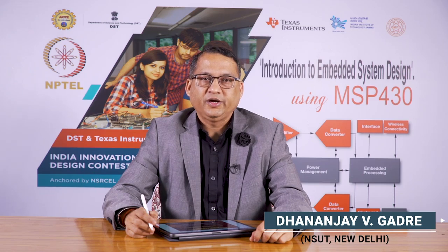In this session we are going to talk about one of the peripheral functions of a microcontroller, namely communicating with the outside world. If a microcontroller wants to communicate with the outside world, there are many ways of communication, but the common methods require you to send and receive data in a serial fashion. Why? Because it minimizes the number of connections that you would require for communication.